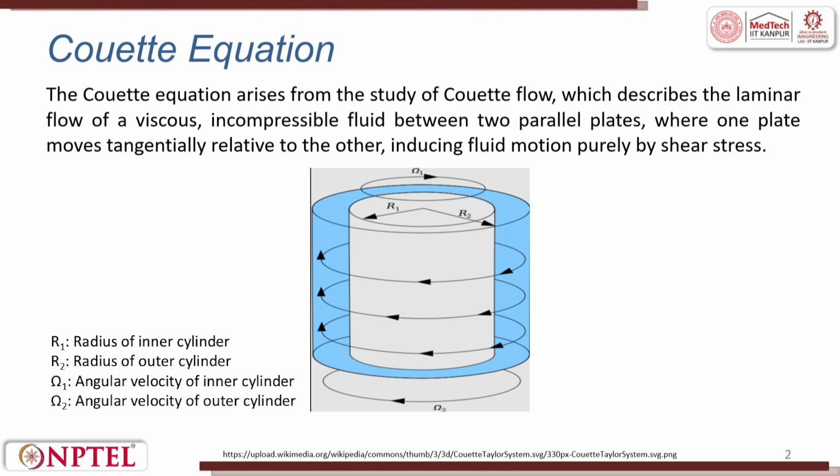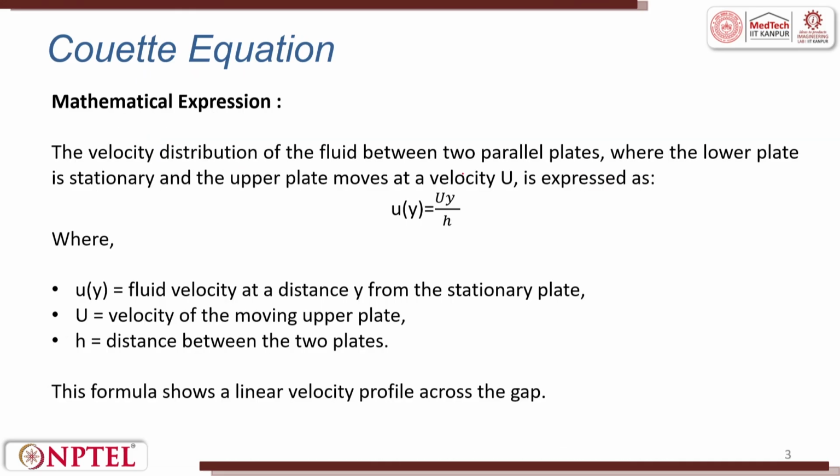To recall the concept of the Couette equation, it arises from the study of Couette flow, which describes the laminar flow of a viscous incompressible fluid between two parallel plates where one plate moves tangentially relative to the other, inducing fluid motion purely by shear stress. Here you can see we have the velocity distribution of the fluid between two parallel plates, where the lower plate is stationary and the upper plate moves at a velocity U.